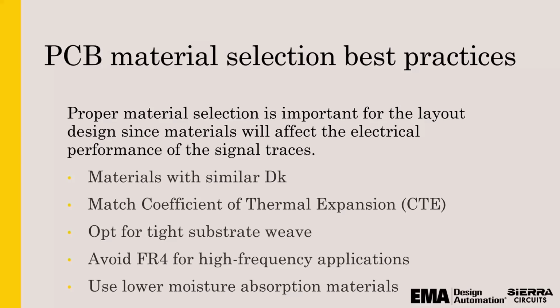So, PCB material selection best practices. I think this is why most people are here at this webinar, to hear what issues to avoid and what I should really consider. We talked about it: material selection is really important for the electrical performance as well as manufacturing. So, with materials, look at the DK, look at the CTE, look at specifying a tighter weave for glass, because it performs better electrically.